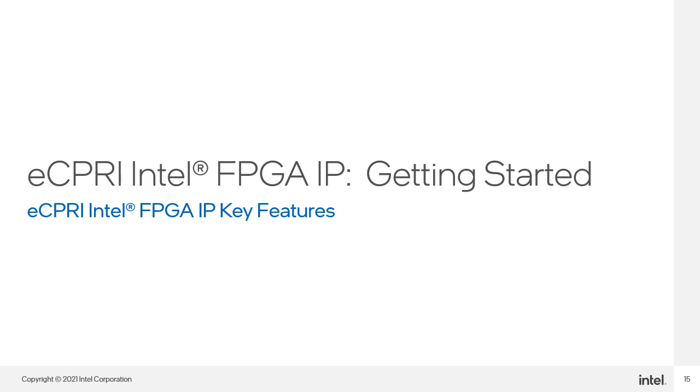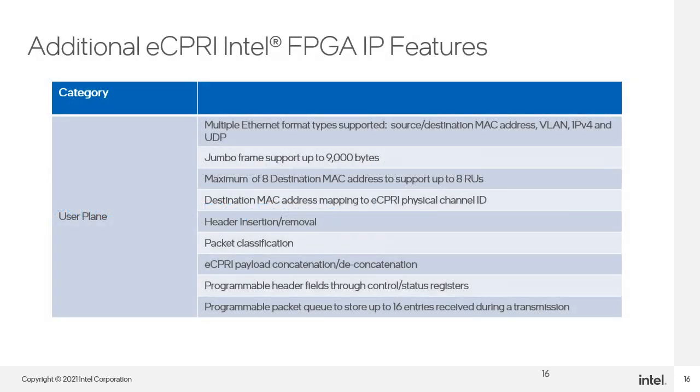Now that you have a good high-level understanding of the eCPRI IP and its place in the system, let's look at some of its key features. The table on this slide and the next summarize some additional features of the eCPRI IP. The IP supports multiple Ethernet frame types, including source and destination MAC address frames and VLAN frames, along with IPv4, IPv6, and UDP. This includes jumbo frame support up to 9,000 bytes.